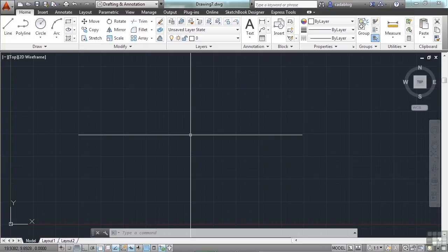Typically, AutoCAD users will work with one set of drawing units, whatever they might be. Sometimes, though, you will need to work with files that are drawn in different units. That's why it's so important to define your units in the Unit Manager. If this is done properly, then AutoCAD can interpret the different units accordingly and scale the line work as needed when you bring it into your drawing. Keep in mind that not all CAD users are created equal, and none of them are as responsible as you are, and they may not have properly set their units. So it's a good idea to check the file before you work with it.